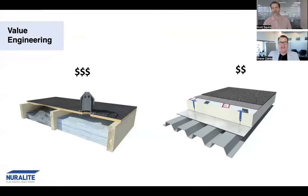More cost differences. Cost difference between the Nuratherm TPO and the 2-layer torch-on. Now, basically, square meter for square meter, the product is very similar. So a square meter of base sheet and cap sheet is very similar to a square meter of TPO when it comes to product costs. The savings come in when it comes to labour and installation. So a large square rectangular roof can be very quickly installed. There's not much detailing, so therefore would recommend TPO. Torch-on can be detailed much easier for a detailed project.